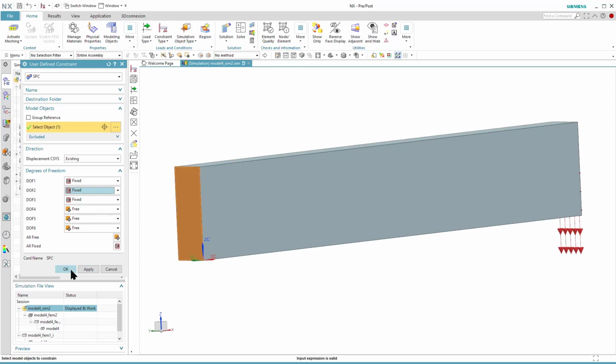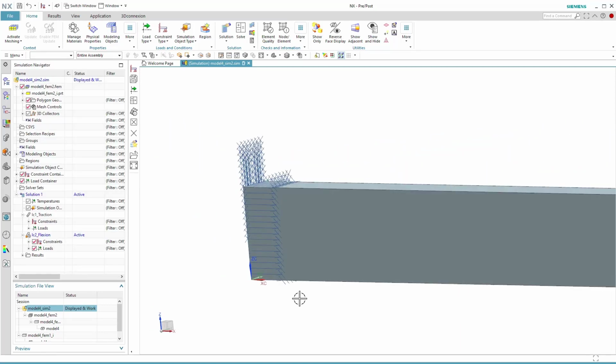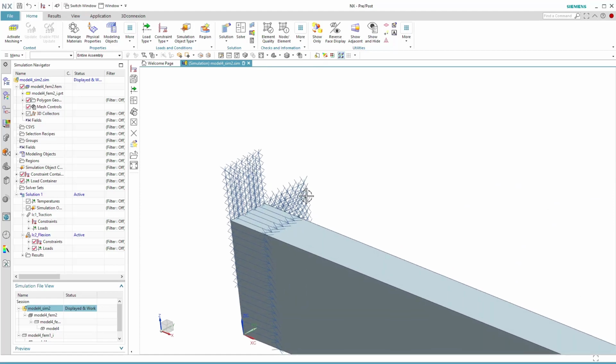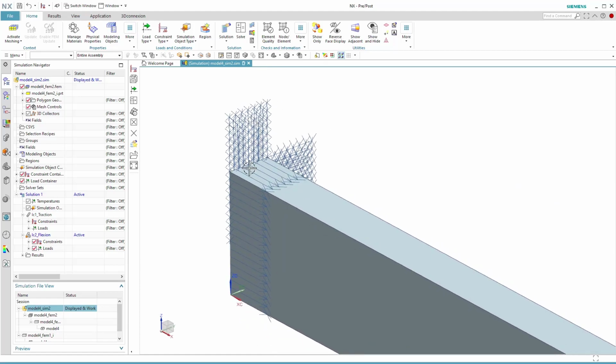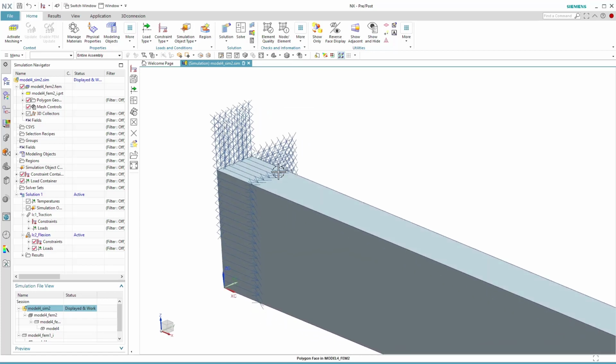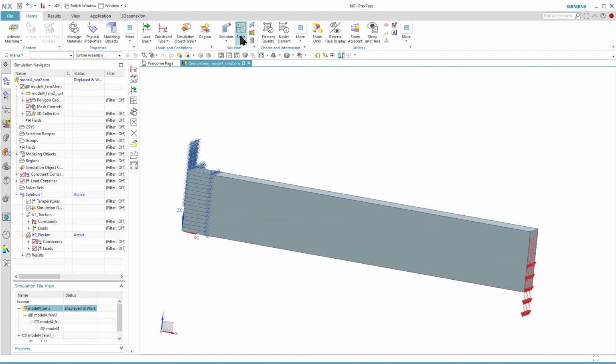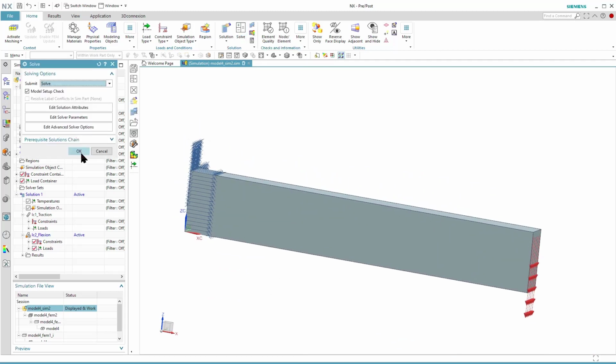In FEM it's possible also to give a translation, not only to give forces. So it's fixed, and you see how it's represented fixed in this manner. You see every node that it is limited in translation. We have just the X cross there, so it's okay. I've done all. I let it solve.